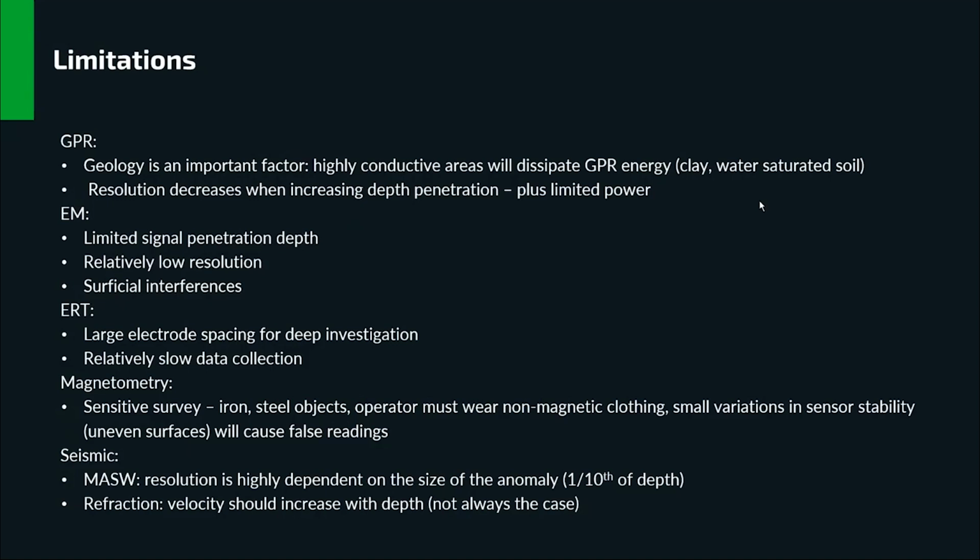In terms of seismic, its resolution is usually dependent on the size of the anomaly, and in the case of refraction, refraction works if the velocity increases with depth. That's how the waves can basically travel along the interface of two different layers.